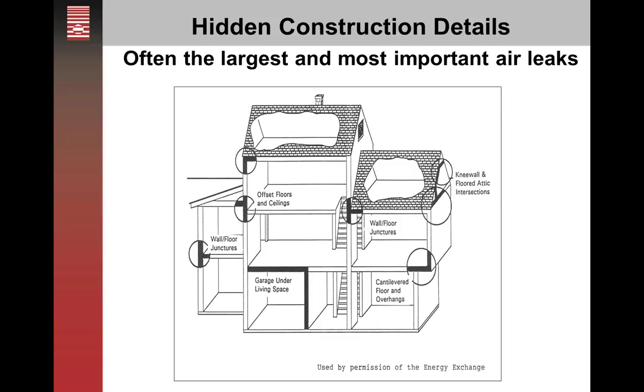Anytime that you have a new roof line attached to a sidewall, or offset flooring such as in a split level house, each one of those is a potential location to look at. Is there a good seal? Is there any thermal bridging? Is there airflow moving across it?